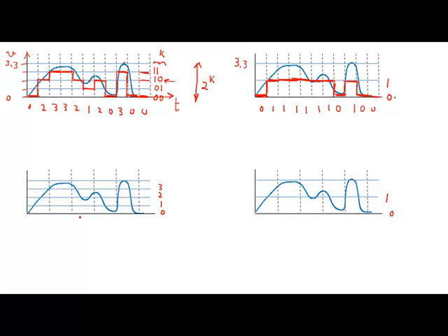So this is not going to be 1 mega samples per second. It is going to be 0.5, or 500k samples per second. So here again you would take the average value, and I'll talk about the physical averaging. The physical averaging is done using a capacitor, but we'll get to those details later.